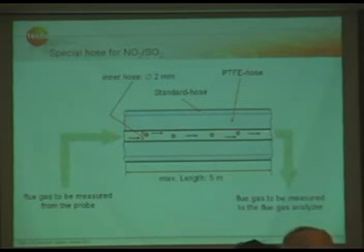Even if we have condensate and flue gas here inside, we don't give the flue gas and the condensate the chance to react together, because of this high flue gas flow or volume flow. There is no chance for the condensate to react with NO2 and SO2. And this is why our readings with our PTFE hose are almost as accurate as using a heated system. And of course, the advantage is you don't need to have AC power on site.